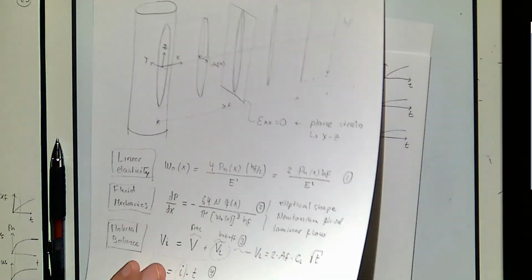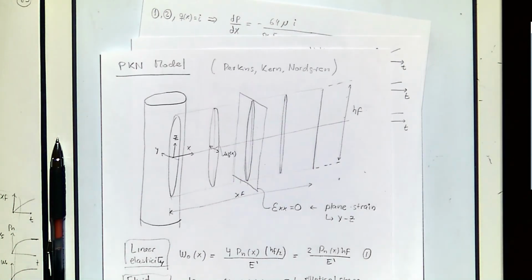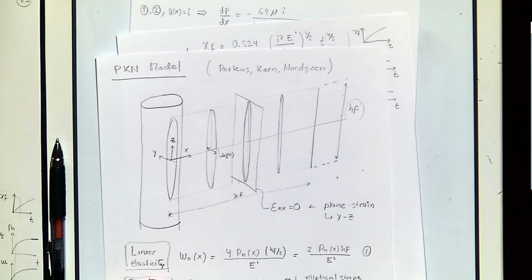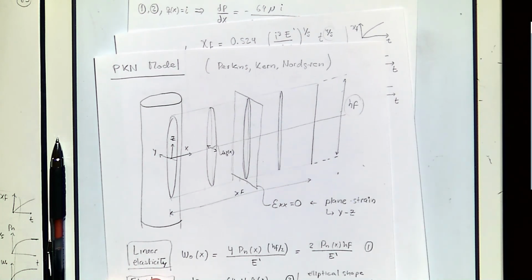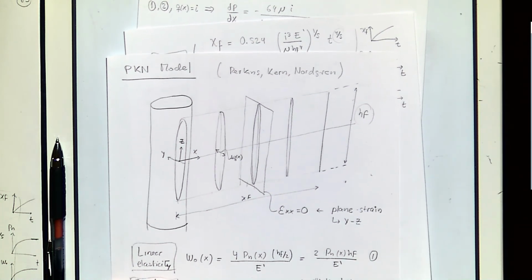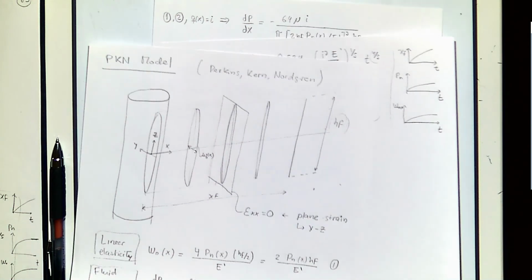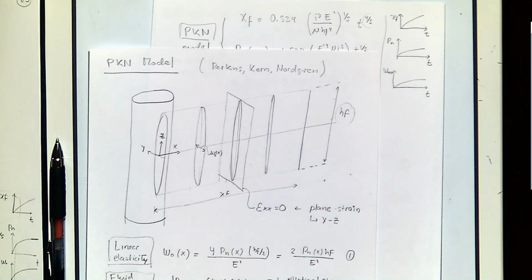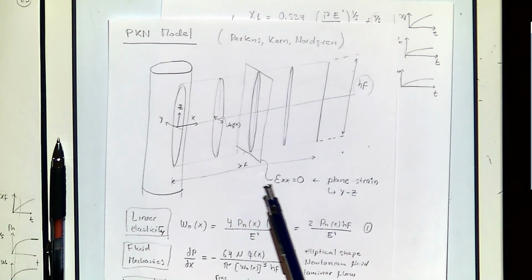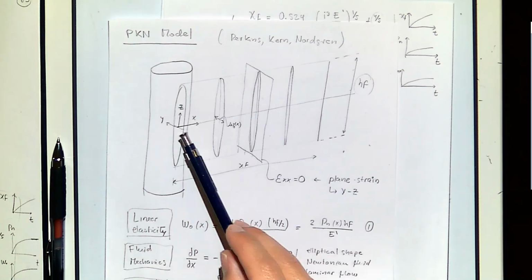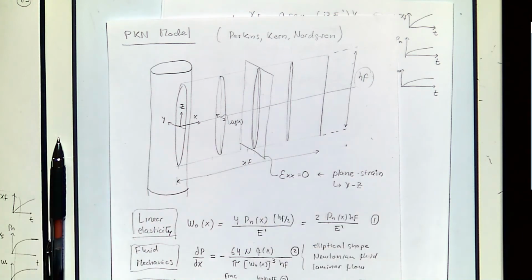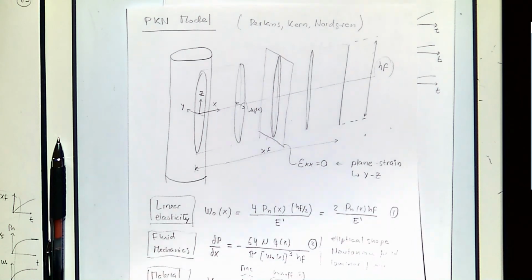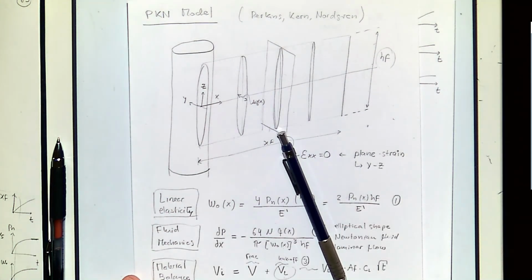So that's everything that you have to do for this simple geometry. And one more thing that we didn't talk much about is fracture height. For this model, you have to tell the equations beforehand what the fracture height is. All of these steps, determining fracture height, pressure, and width for a fracture, are what go inside a hydraulic fracture simulator.